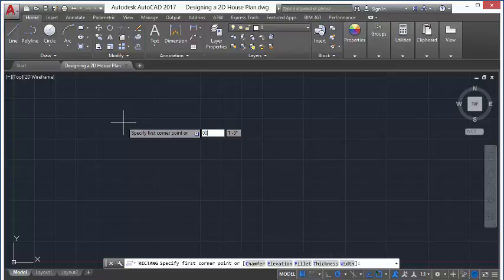But if I enter another 0 again, as you can see, the 0 goes back to the first input, which is the x-coordinate input. So I'm going to backspace once to pull the 1 0. How do I tell AutoCAD that I want to enter the next coordinate, which is the y-coordinate? There are two ways of doing it. Number one, by pressing the comma key or by pressing the tab key. In this case, I'm going to use the comma key.